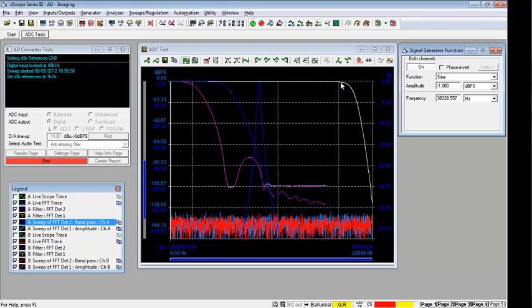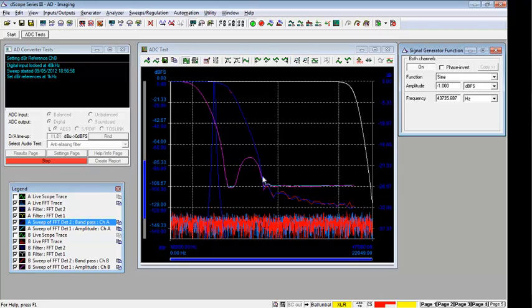So we're plotting two different things. The blue trace here shows us the amplitude of the signal and then the alias component, so it shows us effectively the response of the anti-alias filter, whereas the pink trace shows us an approximation of the audibility of the resulting alias products. So you can see that you get quite a difference between these two different curves here.